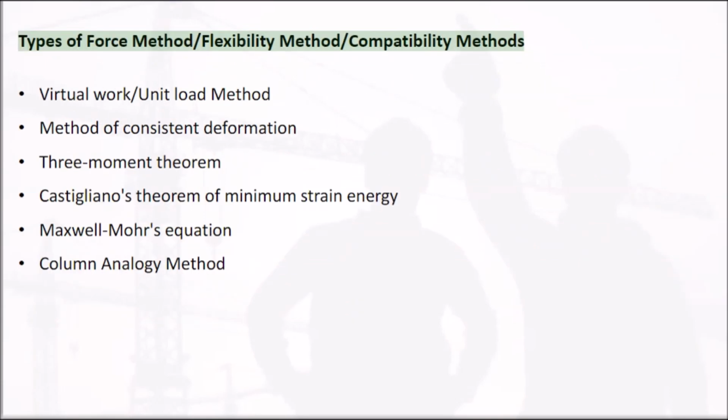Types of force method, flexibility method, compatibility methods: virtual work or unit load method; method of consistent deformation; three-moment theorem; Castigliano's theorem of minimum strain energy; Maxwell-Mohr equation; column analogy method.